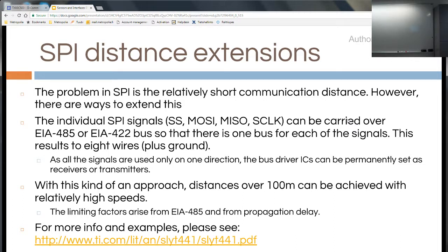So you can easily find these type 485 or 422 bus drivers, technology from the 70s. So that was the extension of RS-232 up to 1 kilometer or so on twisted pair lines with quite poor balancing. But anyways, you can easily get, say, 100 meters or so. There are only the limits basically of the signal.